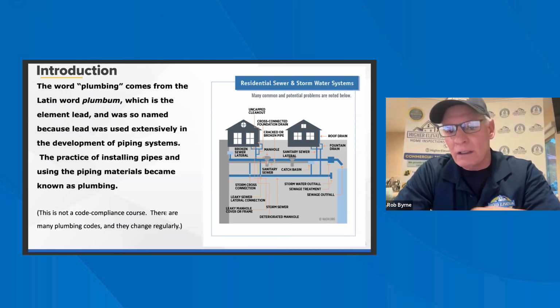Okay, excellent. I love this slide. We talked about the galvanized or steel water main coming in. What happens here is you can see the rust buildup over here. That's what we're talking about with roughness. It's restricting the flow. That sediment, the rust from the inside of the galvanized water supply, is going to affect the pressure.